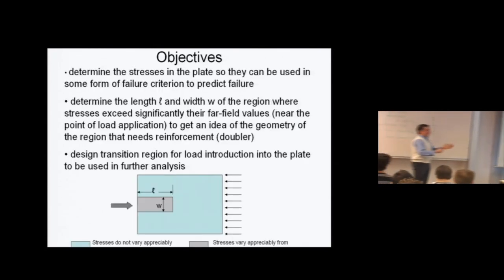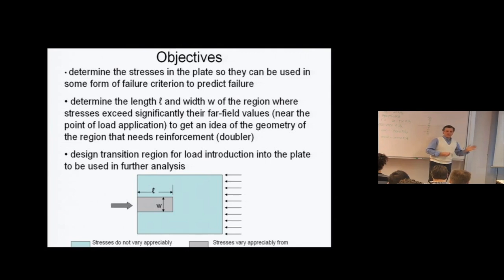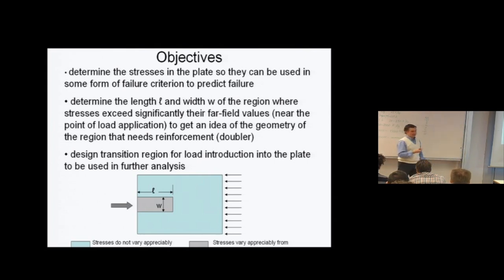Why are we doing this now? Is we're saying, okay, if I know that I'm going to have the stiffeners terminating, most likely right where the stiffener terminates, which is at this location here, the skin, if I designed it just to take the load in the distributed form, would definitely not be strong enough. So I would need to reinforce the skin, and we select obviously to reinforce the skin locally, because making the whole skin twice or three times as thick, while it would work, adds weight.